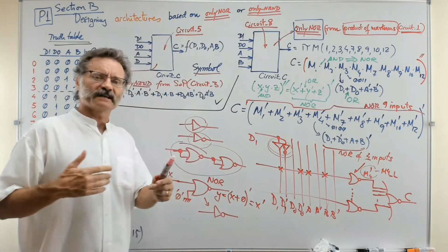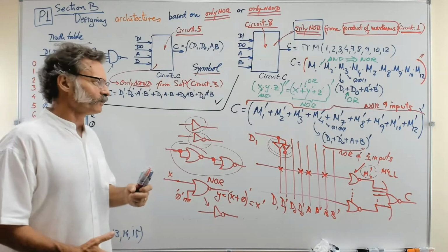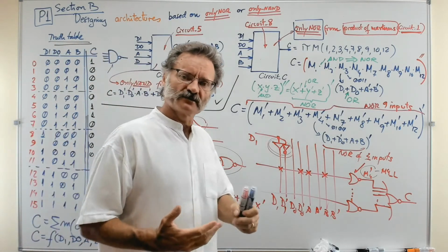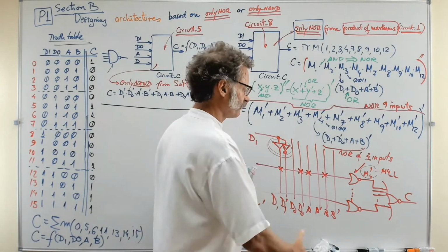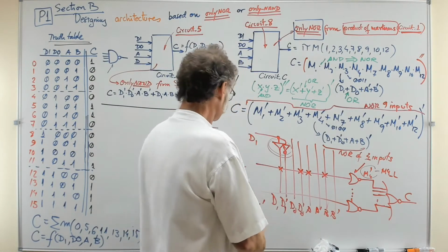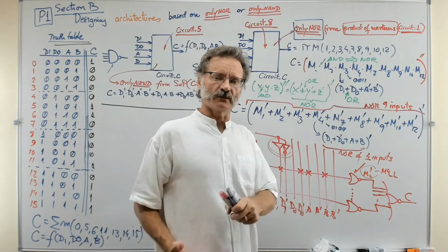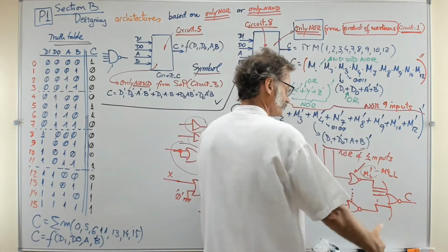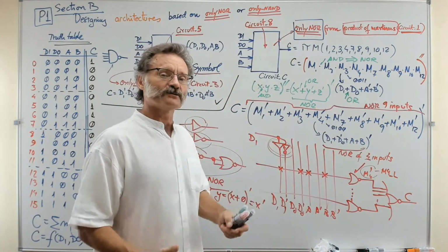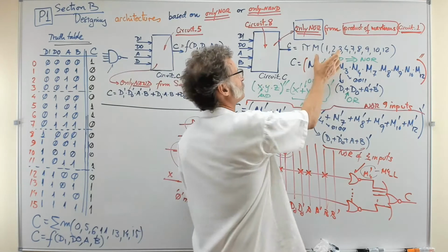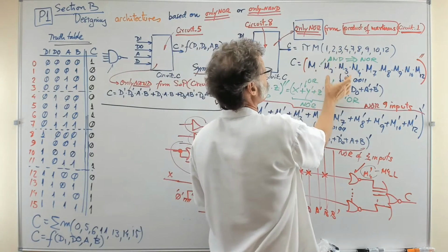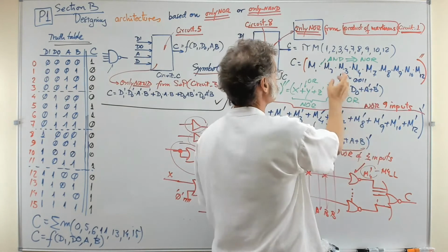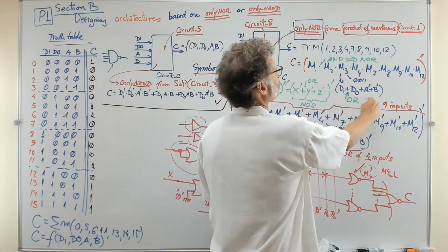Okay, that was very practical some decades ago when people liked to have only a single type of chip in the lab. So you buy chips like this, only type NOR, and that doesn't matter very much because you can invent a very regular circuit, the same as when you are using the typical thing, which is, for example, like here, not buffer, first level of gates, and then ORs and AND.